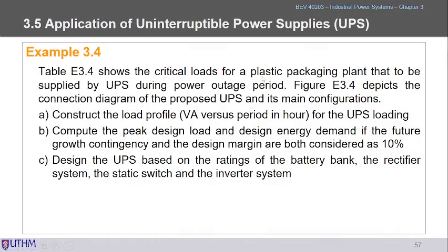Okay, we look back at the questions. The question is we need to construct the load profile, which is plotting VA versus the period in hours. This is the autonomy hour, VA versus the autonomy hour for the UPS loading. This is task number 1.